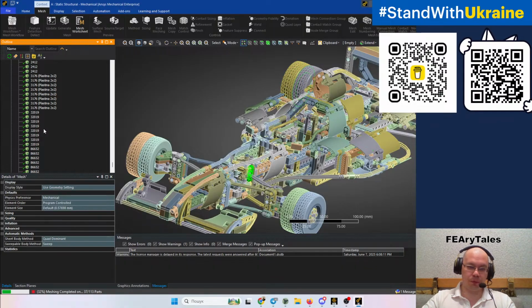Some of these objects need to be deleted from the model because they don't give any additional useful information for the behavior of the modeling in most cases, like imprints, embosses, small fillets, holes, and so on.